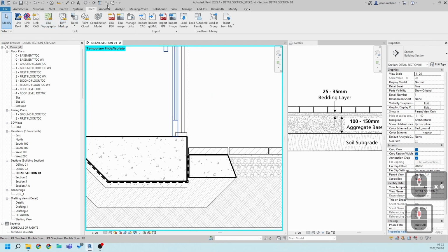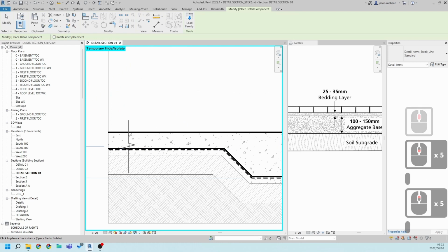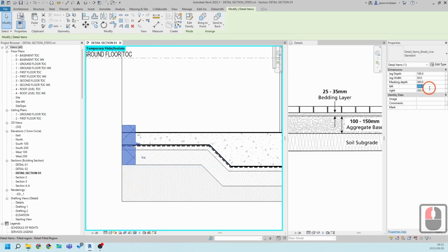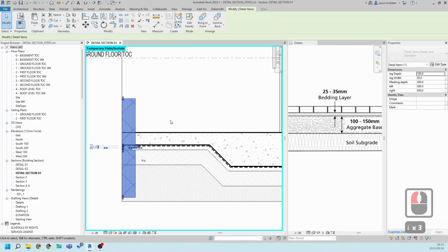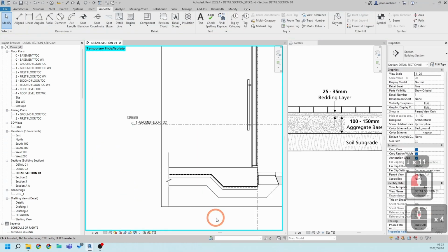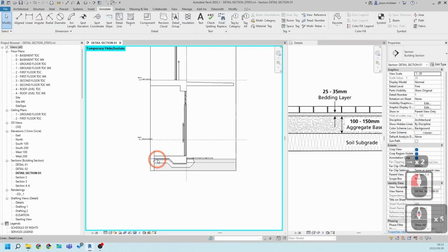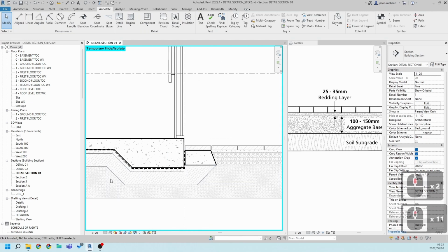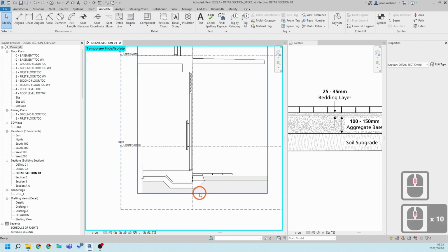In this view, you can go to Annotate now, Component. Now you can use this breakline tool. Spacebar allows you to rotate. So now I can use this breakline tool. And here you can adjust the left and right, so make it 500, 500. You can adjust the sizes of pretty much everything here, so you can put this information just like that, and you can start copying this information up and down. So you can literally start copying this information up and down. Go and add as much detail as you can as per my example.